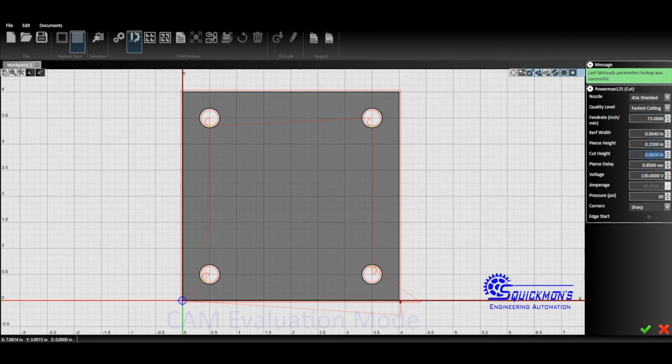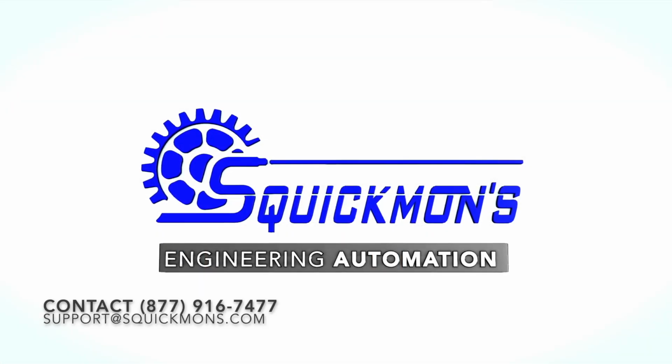These are set directly from Hypertherm's book callouts. You can modify these as you see needed, but we strongly recommend just starting off and building comfort with the machine and confidence in operating the machine, and then as you grow in it, you can start to change these parameters as you need to increase your cut quality, because it takes a little bit of time to learn what to increase and what things to change to increase that quality.